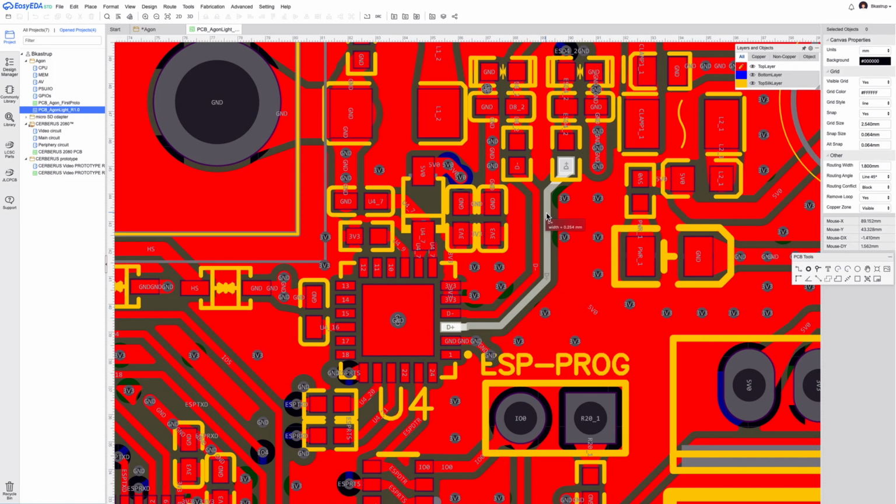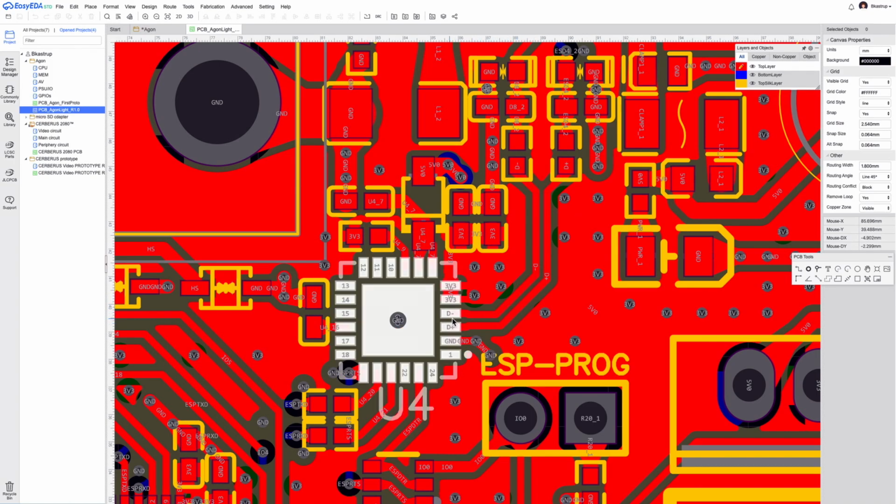So this is a difference with respect to any other lines. You don't want two lines that are unrelated to one another to be routed close, because if they couple to each other, that's a form of interference that we call crosstalk, and we don't want that. But in the case of a differential pair, that's precisely what you want. You want to couple them, to have common mode. It works like a very small inductive filter of interference. So we keep them routed together until they connect to the USB bridge in here.